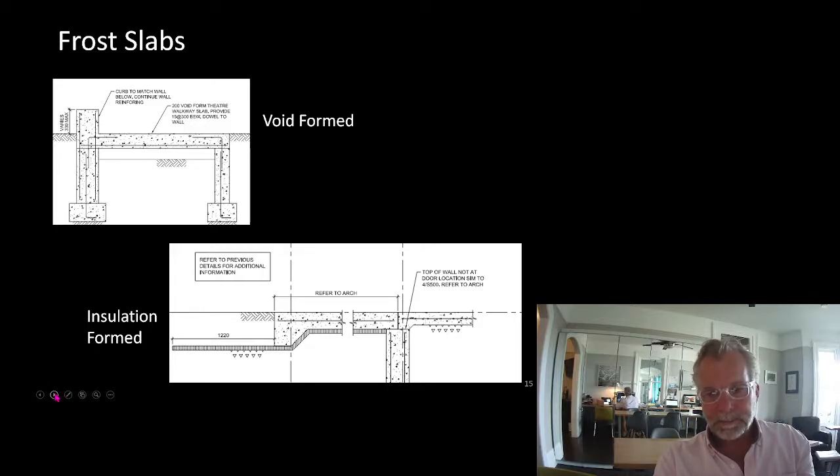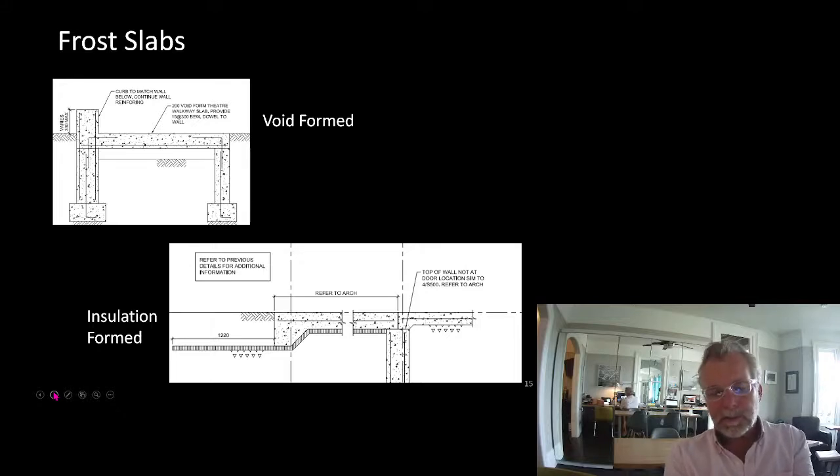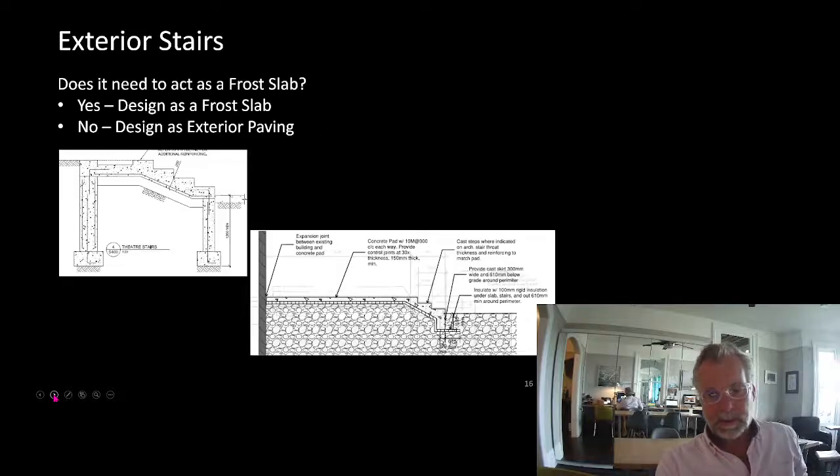common standard now. And so you can see what's happening here is that this slab sits on grade, but this grade is protected from freezing by the insulation, and therefore there's nothing that tends to make it heave. This doesn't work everywhere. So we're doing a project in Winnipeg right now where all the soil in Winnipeg is expansive clay, and that clay is going to move up and down, or the ground surface is going to move up and down with changes in moisture content in the soil regardless of frost. And so we can't do a detail like this, or it's inadequate.